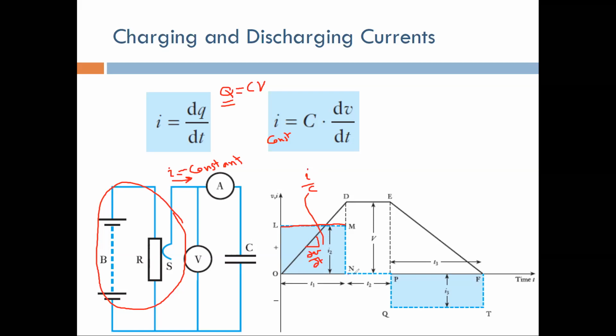If you turn off the current, if the current is 0, then the charge will just stop. Basically, if you have I equal to 0, then dV/dt is equal to 0, meaning that it's not going to change. The voltage will remain the same, so it's going to remain constant. When you stop the current, there is no more change in the charge. You're not charging the capacitor anymore, so it's going to keep the last value of the charge and continue like this until another change happens. So if the current is 0, the voltage will be constant.